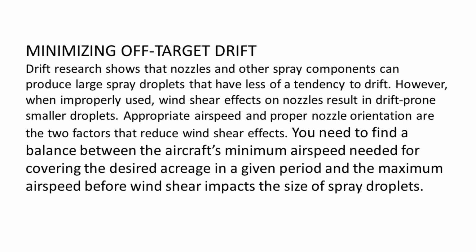However, when improperly used, wind shear effects on nozzles result in drift-prone, smaller droplets. Appropriate airspeed and proper nozzle orientation are the two factors that reduce wind shear effects. You need to find a balance between the aircraft's minimum airspeed needed for covering the desired acreage in a given period and the maximum airspeed before wind shear impacts the size of spray droplets.